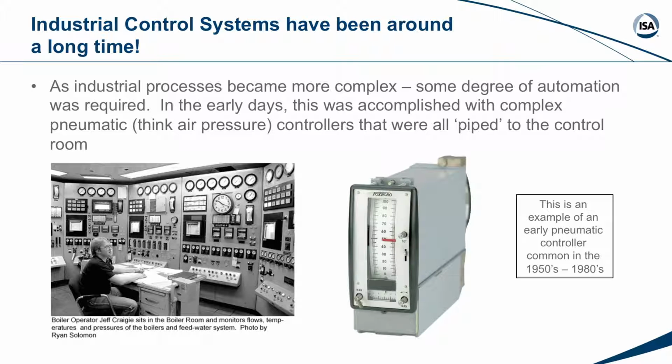And I'll tell you, when you looked at some of the tubing installations in big installations, they were like a sculpture. Thousands of stainless steel tubes all coming into a central area and all going back out. We tuned those just like proportional integral derivative PID controllers, right? They had settings, they had set points, they had changes. You could put them in manual, take over the valve, you could put it in automatic.